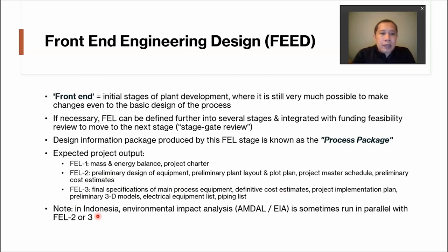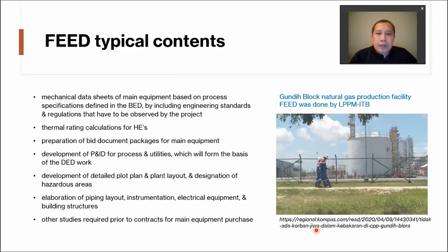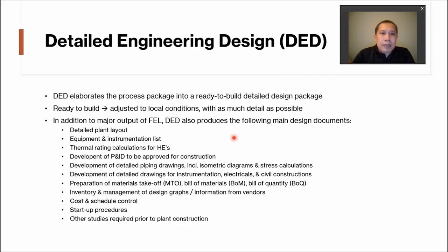And as a side note, in Indonesia, AMDAL, or environmental impact analysis, is sometimes run in parallel with FEL2 or 3. Okay, so this is the typical content of a FEED: mechanical data sheets of main equipment, thermal rating calculations for heat exchangers, preparation of bid document packages, development of PNID, and so on. Okay, I urge you to read more about these outputs of FEED project.